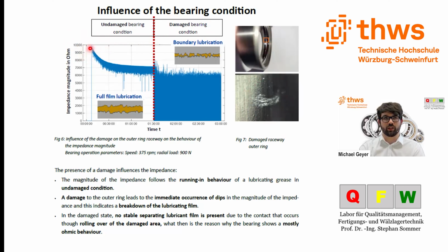This was done to secure the measurement signal against influences of external factors and partial or complete loss of the signal. So how does this measuring system get us our impedance values? Well, the impedance is a value that is not directly measured, but is calculated through an implied alternating voltage and a corresponding alternating current. The HCP system uses the same technique and applies a high frequency but low alternating voltage at the contact points and measures the flowing current. The important part of the measurement is the insulation of the signal from the environment, like we did to secure the measurement of the test bearing.